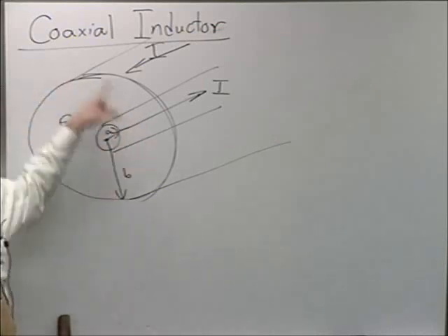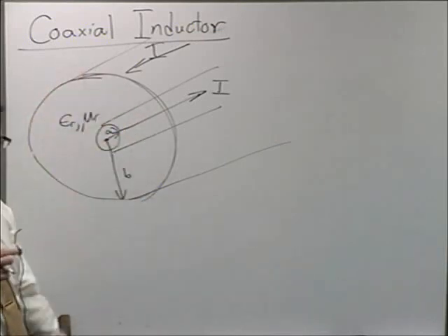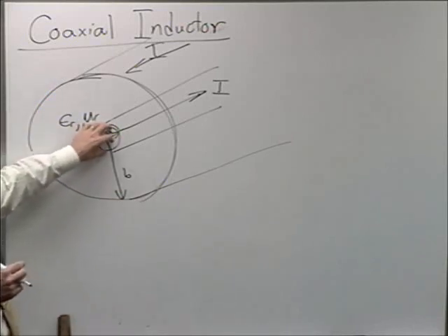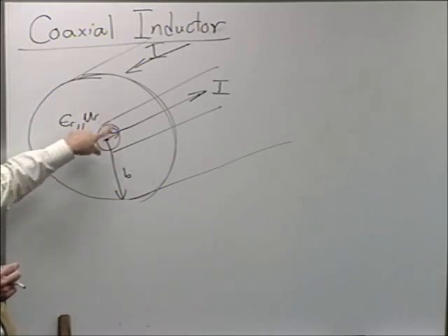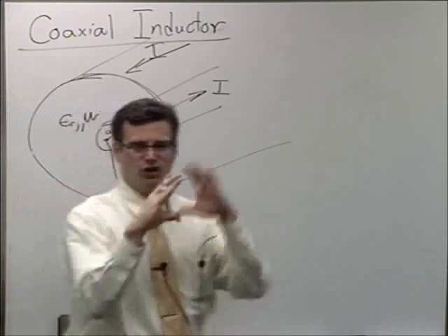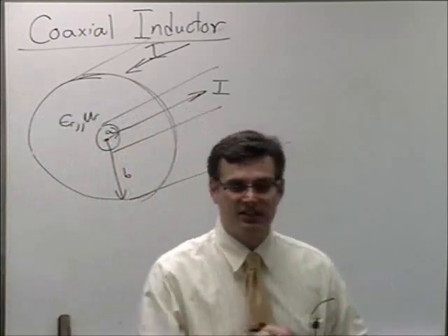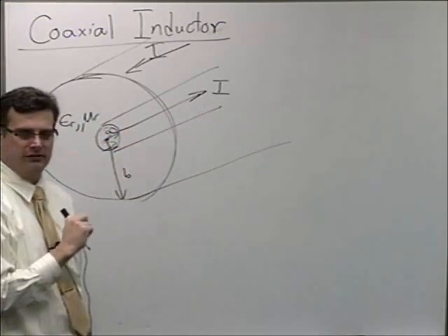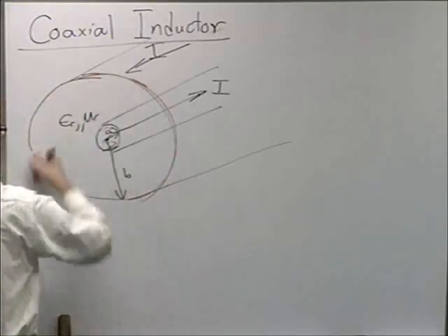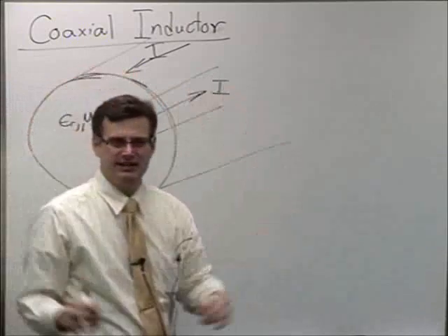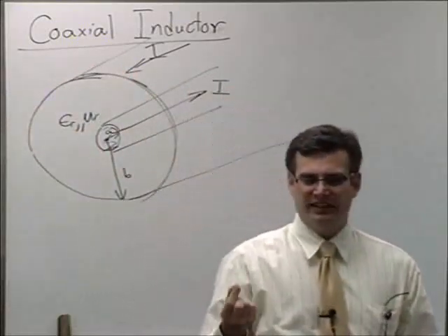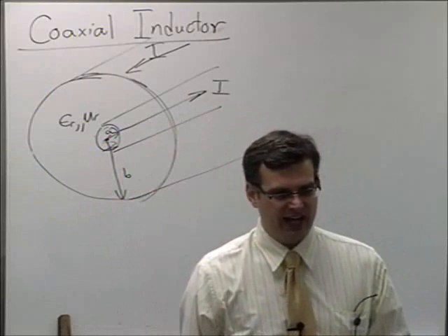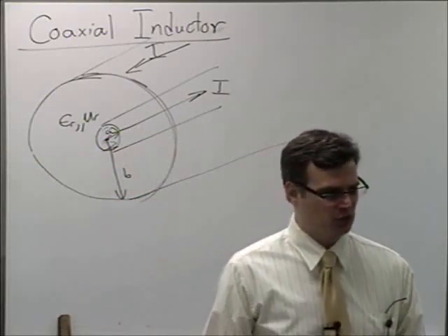That improves the resistive properties of the outside of the coax. This is sort of the bottleneck in your conductive path. So it's the losses of the inner conductor that give you most of your ohmic losses. Current's confined to a tighter circumference. Remember, because of the skin effect, this actually isn't going to be a volumetric flow, even if this is a solid piece of metal. It'll all be on the outside, pretty much. Likewise, this sheath of current will all be uniformly spread out on the outside. So that's why a lot of times you'll see really nice copper or brass or whatever used on the inner conductor, and then they just throw some cheap braided aluminum on the outer conductor, because they don't care. They just want to make that cheap.